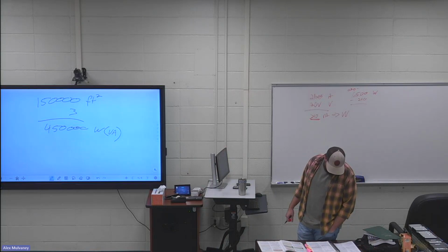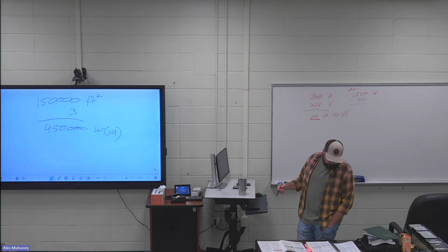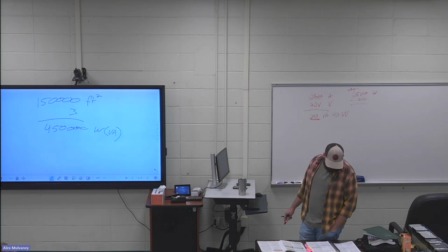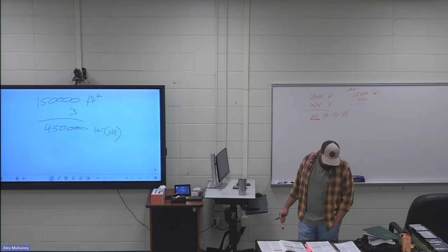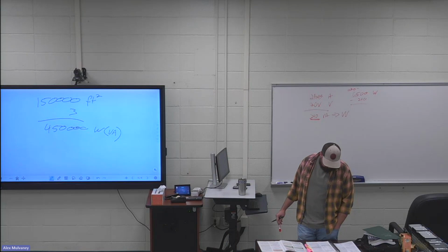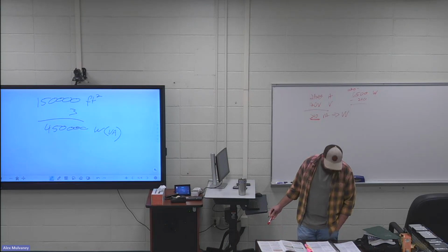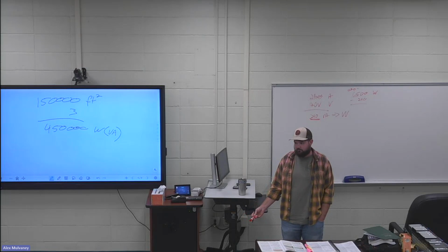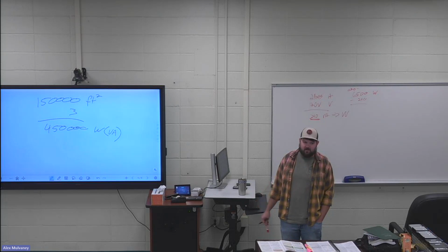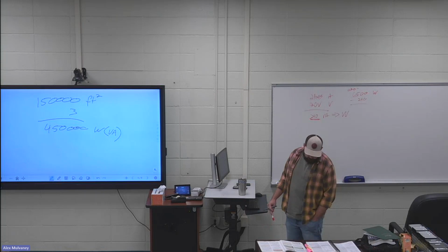So you can see a manufacturing facility is going to need 2.2 volt amps per square foot. Or down at the bottom, a school or university is going to need 3, whereas a lower number would be like 0.3. Parking garage. What do you have in a parking garage? Lights, right? Pretty much just lights and maybe a few plugs, maybe a fan, but it's not going to take a lot of electricity. Does this make sense? All right.